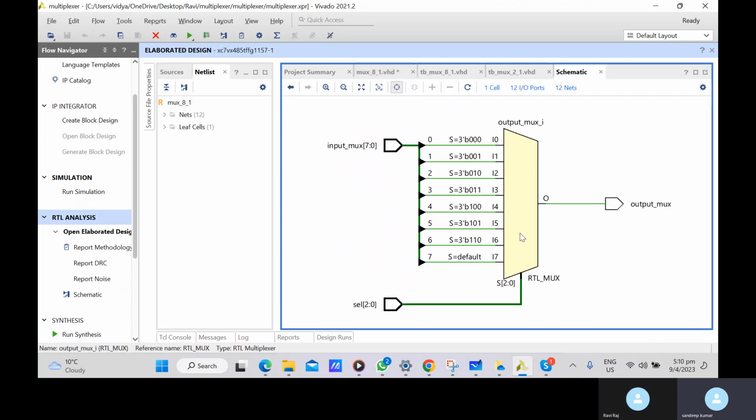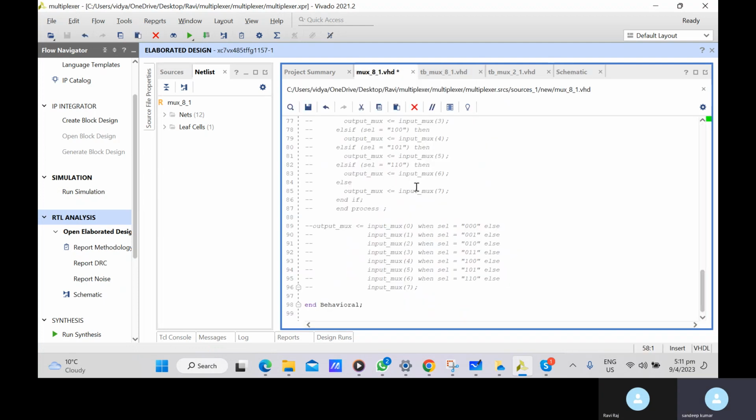Once a parallel mux is there, it is always fast. Why fast? Because it is implemented in parallel, so each path has almost similar delay, except the decoder part. But if-else is sequential, a series. If we select the last output, select 7, it has to go through so many muxes, so much hardware, and it will arrive very slowly. Input to output transition delay is very high. So this is an inefficient way of writing.